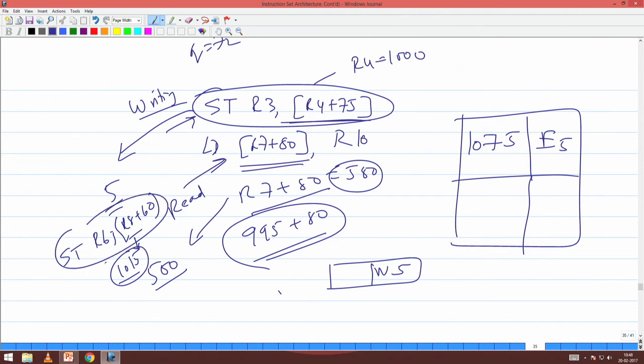Suppose this store is currently allocated to execution unit 8. Then you just make this E8, that is all. We handle two fellows writing into R1 also, so all the subsequent instructions beyond that should do this. But when you are writing back, the reorder buffer will see that it is committing the latest value.